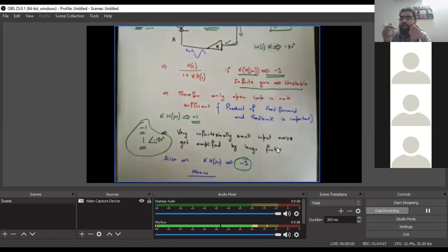And we reach this point whenever in the feedback system the loop transmission gain, the product of the feedforward and feedback gain, is equal to -1. The system is unstable. From the Bode plot, this means whenever the magnitude response value is 1 and the phase response value is -180 degrees, or anything bigger than -180 degrees. Is it clear?